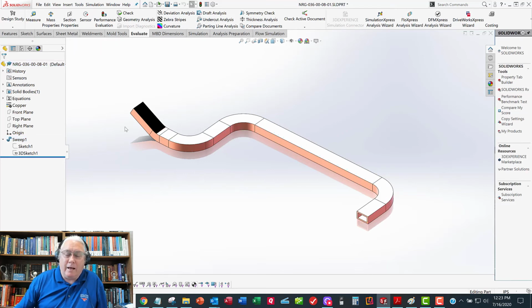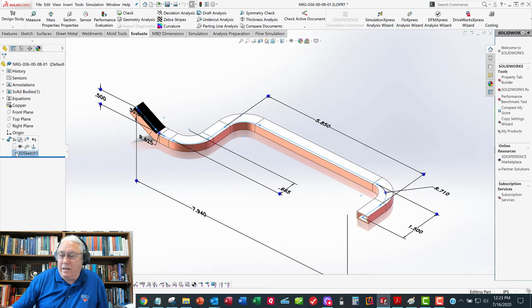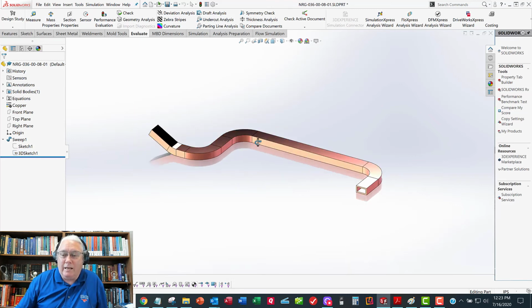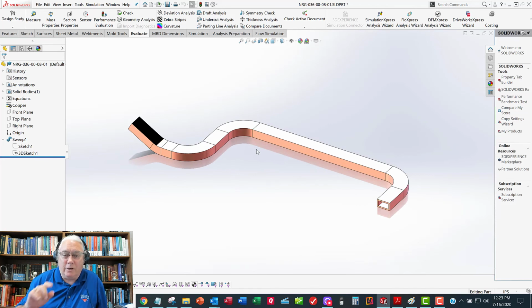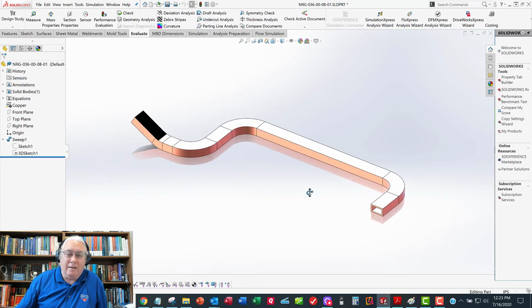So you need to think about how you're going to put in numbers for this radius and this radius. This radius, this radius, and this radius looking down from the top are all equal, and this radius looking in from the front is a different number. But they're all related to those parameters. You need to tie those parameters. So you need to edit your 3D sketch, edit those fillet values, and your part will update correctly. All right, so that's the waveguide part.